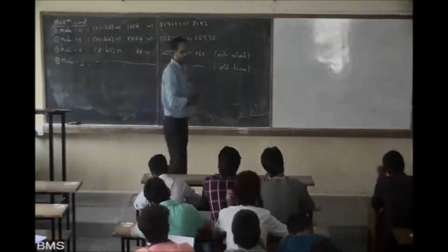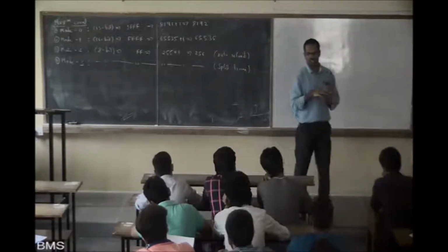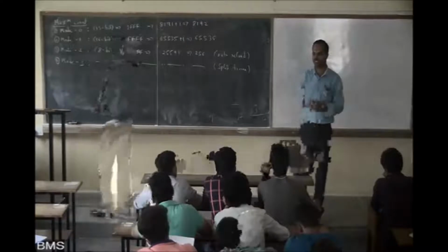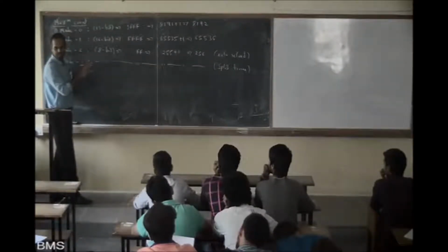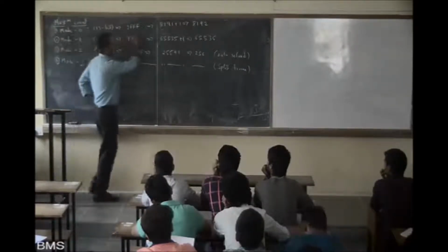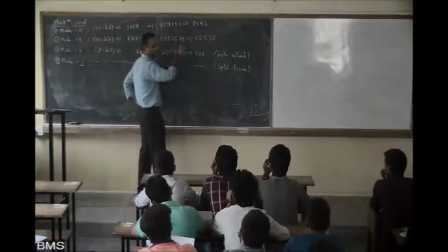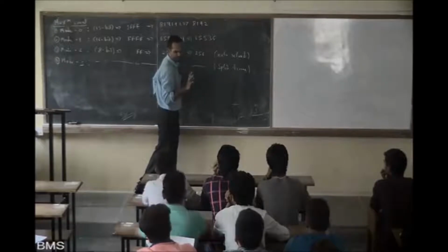Now we'll keep connecting this. You should be careful. At every point you should have clarity. Now we'll take this count and do the next calculation. Any doubt in this? All of you are clear? It is simple. In 13-bit mode, 1FF is the maximum number. The decimal value is this. Total plus 1 is because it starts from 000. 8192 is the maximum possible count.